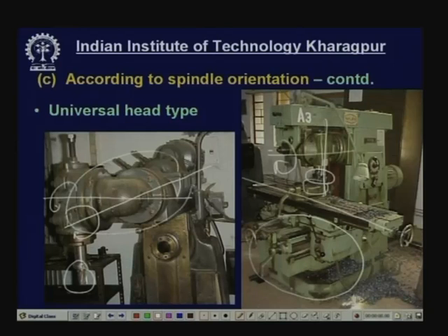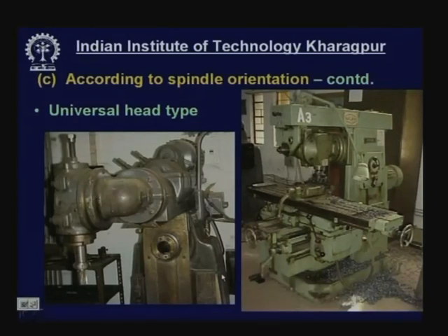In addition to this system, where you can mount cutting tools like end mill cutter, shell mill cutter, face milling cutter, you can also have another spindle for an arbor on which some disc type cutter can be mounted. So, this is a more versatile and capable machine.